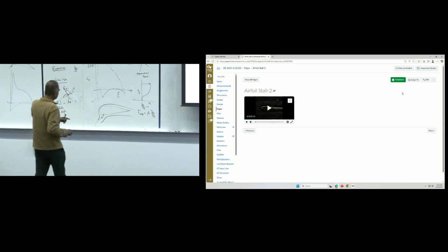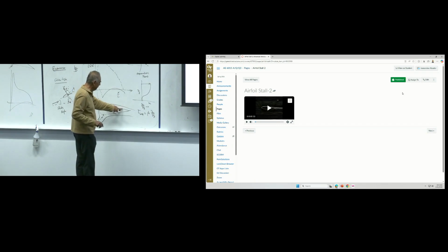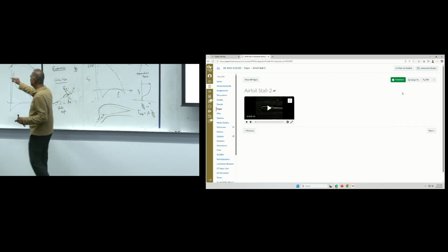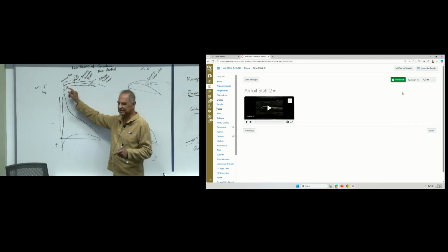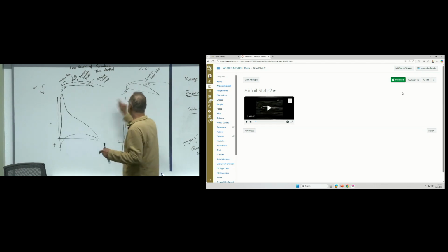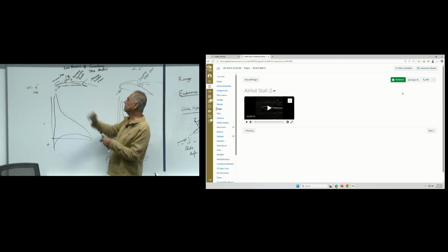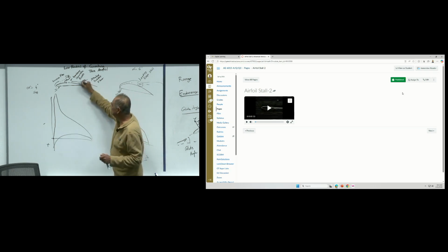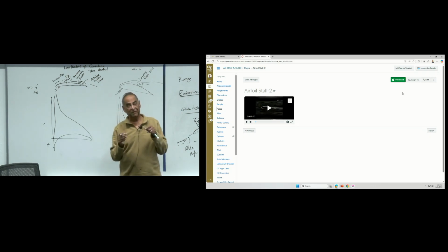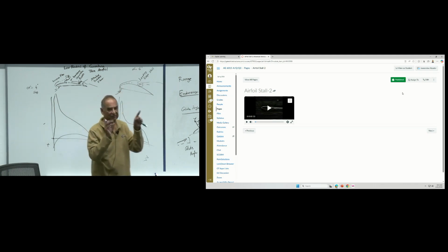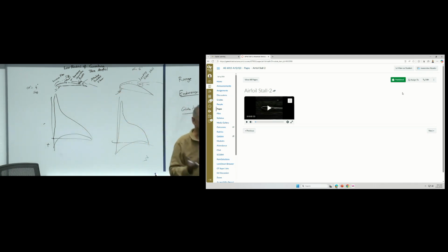If the separation occurs at the trailing edge region and progresses forward, that's a trailing edge stall, which is preferred. But for certain sharp nose airfoils or small leading edge curvature airfoils, that separation may occur right near the leading edge, in which case it may produce a small bubble. Downstream of the bubble, everything starts going from left to right again, but the flow is turbulent. Okay? So turbulent flow reattaches. At higher angles of attack, it may abruptly separate from the leading edge, and it may become a leading edge stall. Okay? So these are some of the concepts we should become familiar with.